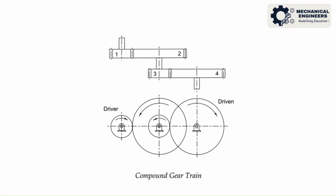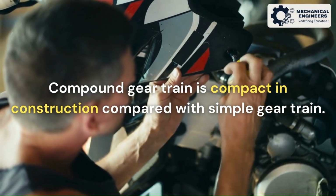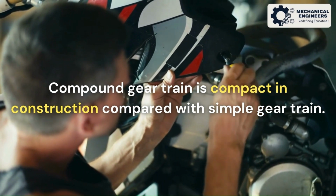A compound gear train is one in which at least one shaft carries two gears. In a compound gear train, the intermediate shaft has two gears, one meshing with the gear on the driving shaft and the other meshing with the gear on the driven shaft. A compound gear train is compact in construction compared with a simple gear train.